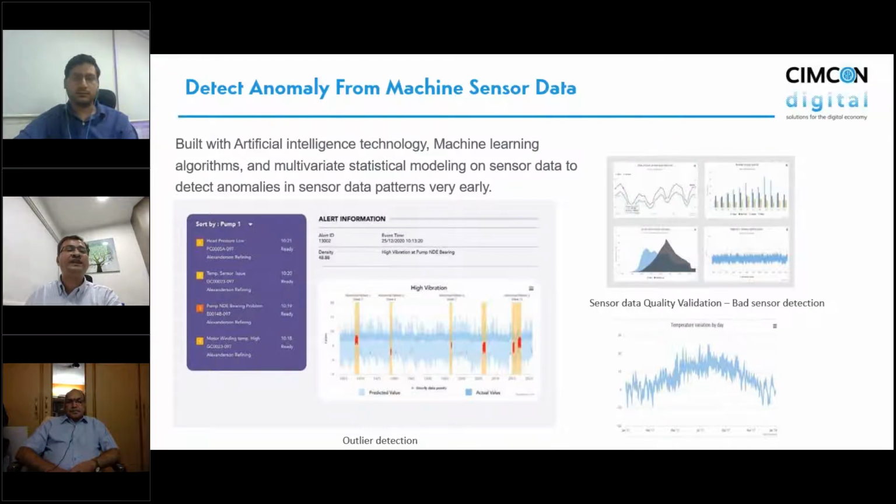For example, when you are running a centrifugal pump in your water treatment facility or your building facility, and the system tells you that your x-axis RMS or bearing temperature has started increasing, and also tells you which particular fault may have started evolving, which helps you to start observing the machine very critically, and then prioritize work orders based on the machine condition.